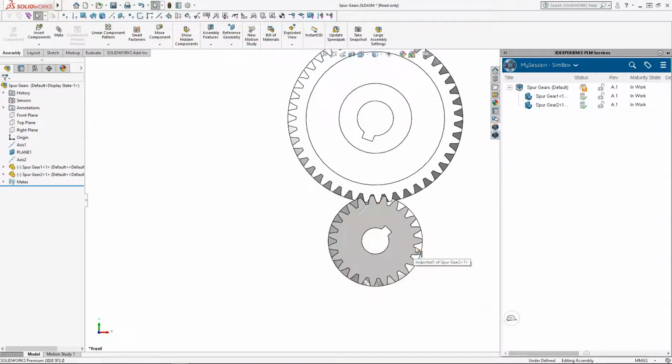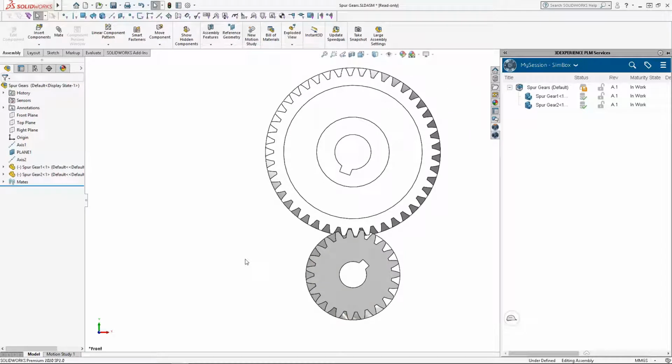Now, if we were going to solve this inside a SolidWorks simulation, first we would resolve the interference fit, then we would apply the rotation, but it would require specifying contact pairs where the teeth are interfering, as well as the contact pairs for the teeth as they're rotating, right? So, this face is going to come into contact with this face with this one. There may be some easier ways to do that, but that's kind of the steps that you would probably take inside a SolidWorks simulation. When we pull it over to Simulia, we don't have that requirement. So there's a huge time savings just in the sense of contact.